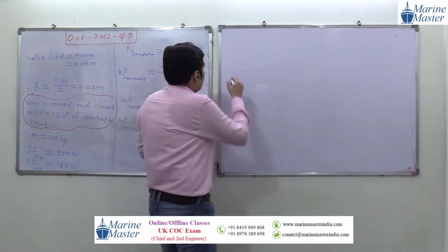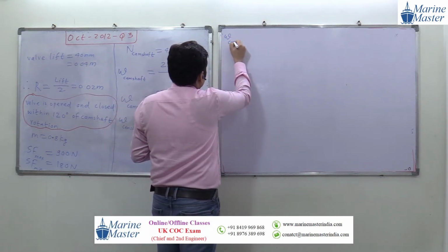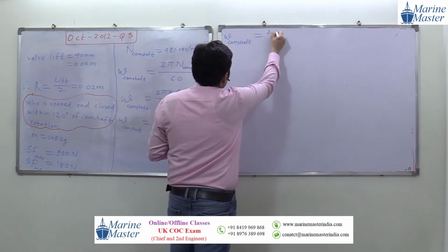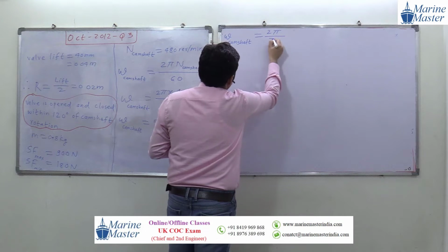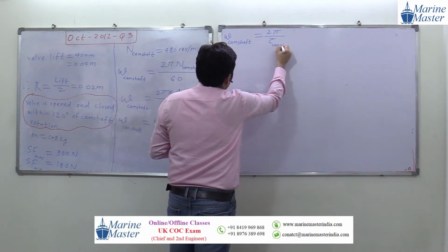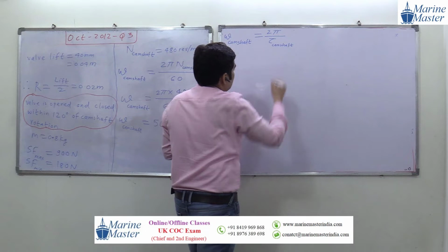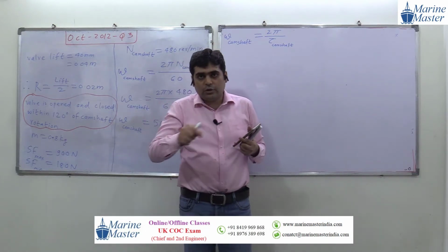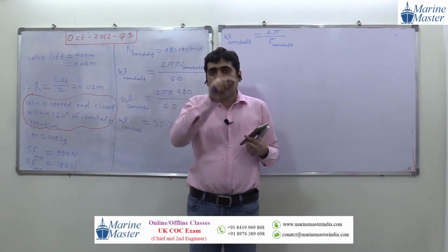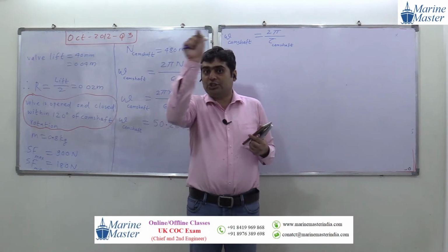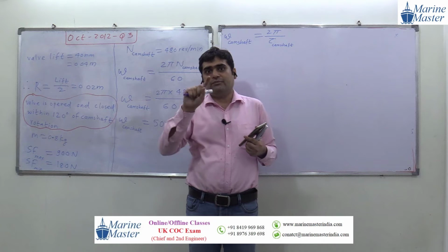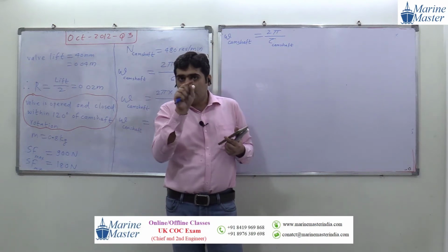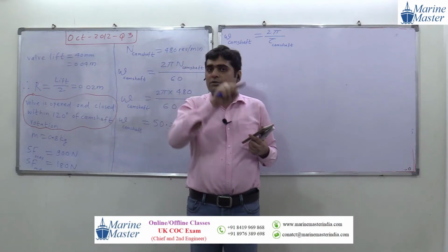Now omega camshaft will be equal to what? Another expression for omega camshaft is 2 pi by tau camshaft. Everyone getting my point? Try to see the scenario here. 2 pi means 360 degree, and tau camshaft means the time required for one rotation, that is, for the 360 degree. Tau means time period. So one cycle of the camshaft is one rotation.